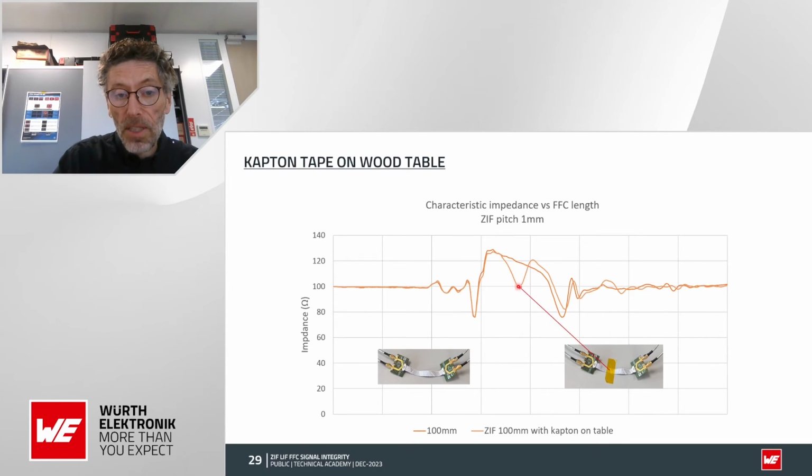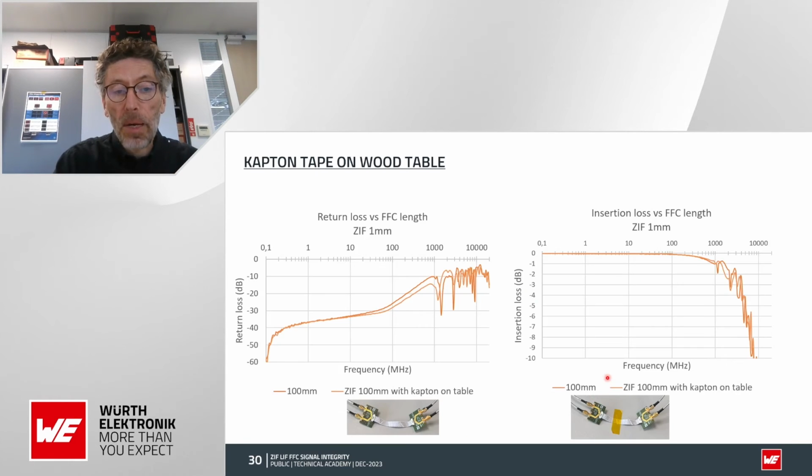You have an impedance change because you change the permittivity of the environment of the signal. Does it have an impact? Not really. So you do not really have to consider that. The insertion loss is a little bit different, but not so much. So if you do not want your FFC to be moving up and down, then you can do it.